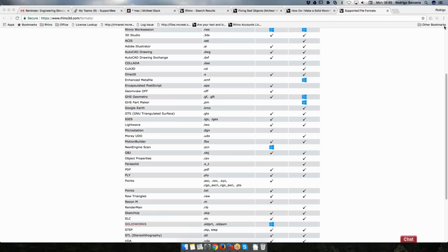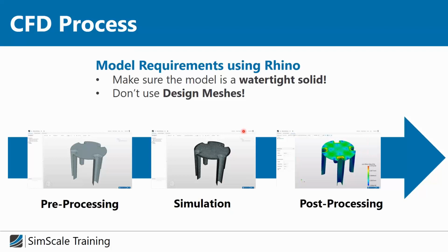For sure, Rodrigo. Thank you very much for this presentation. And again, I think you shared the most relevant tools and procedures to simplify a model for simulation. And guys, this is really 50% of the work. It sounds very strange, but it's really like this, because just imagine you have a very small hole inside this model. You will never be able to calculate structural behavior until it's closed. Or especially what you showed at the ending, joining coplanar faces can be very helpful in reducing our work.